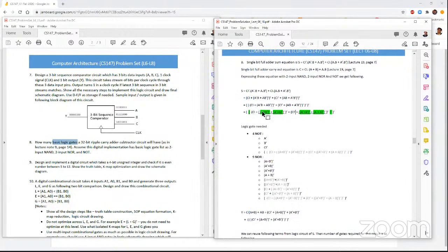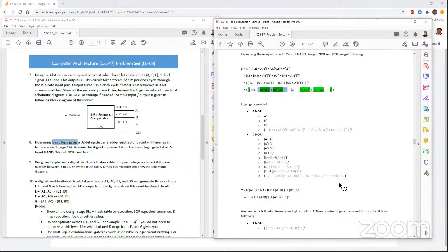And then we are counting the NOR individually. So this guy, all this highlighted one. And then this part is also a NOR. Practically it is NORing between the result of the inner NOR. So that's what I am showing here. Maybe that was the part of the confusion, how this is represented. This is just to explain how you count the gates from a given logic expression. So we come up with 9 NOR there.